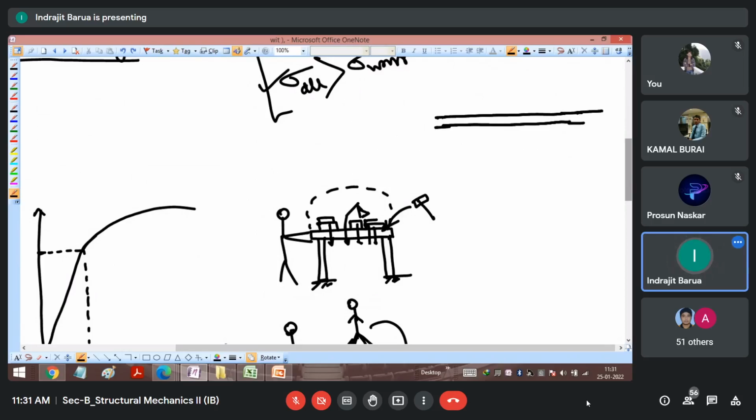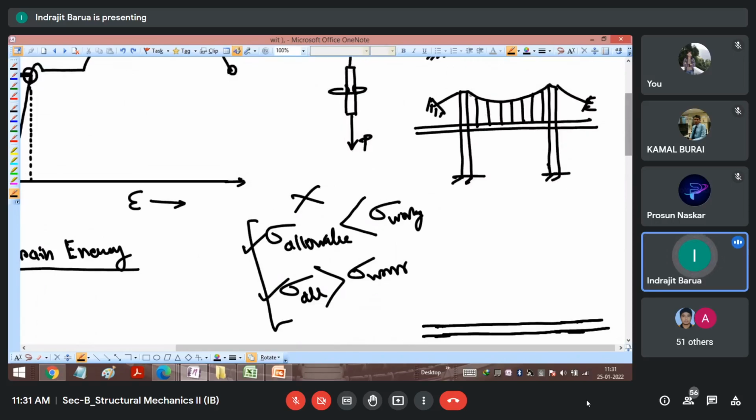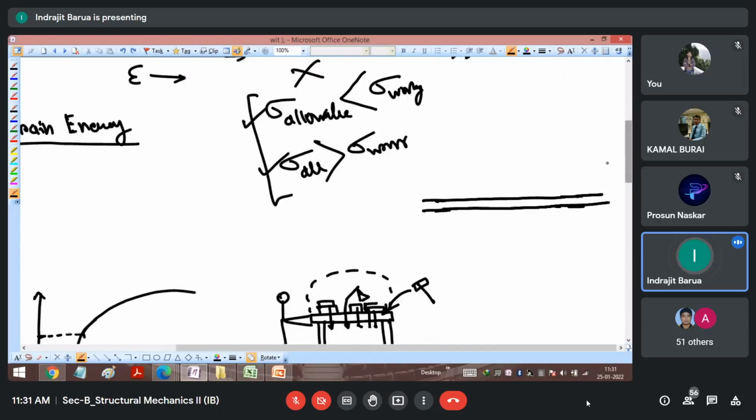Don't worry about it. You will be studying it. You will be doing just great. So basically, we just need to see what this is. These are the main cables. This is the main cable. These are the suspenders, and this is the carriageway. Basically, here the cars are moving, or some train may also move. You just need to take that load into account. And these are the suspenders which are transferring the load to the main cable. The main cable is transferring the load. This is the rigid support. That's it. For study, this is not a very complex model.